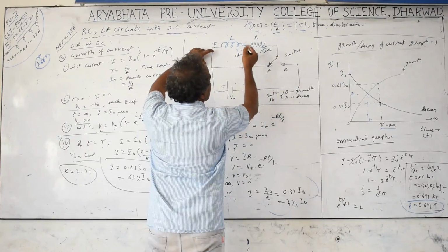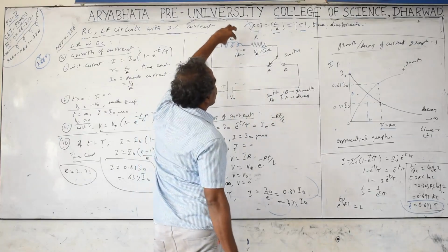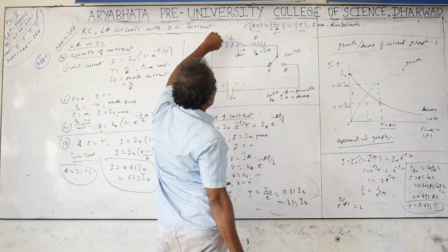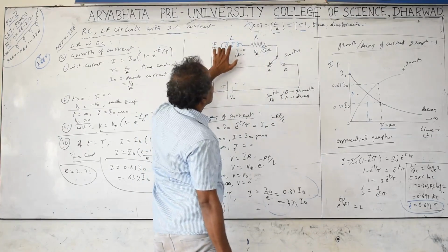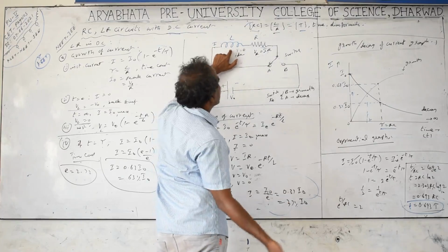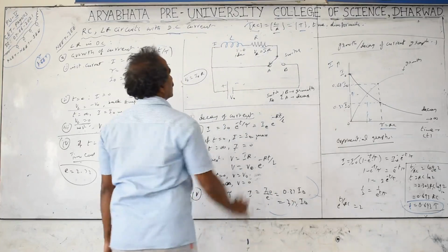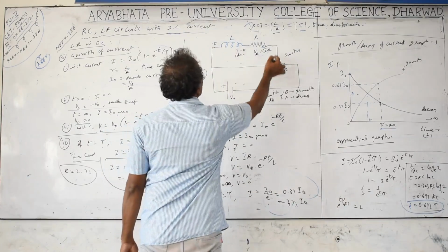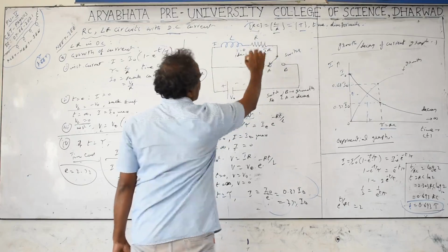It already has current stored in the form of a magnetic field, magnetic energy. Now the current will try to decrease through the inductor. When the current tries to decrease, the induced EMF is a forward EMF which opposes the decrease of the current. But it cannot stop for a long time, and the current will slowly decrease in terms of the resistance. More resistance, less time it takes; less resistance, more time it takes.